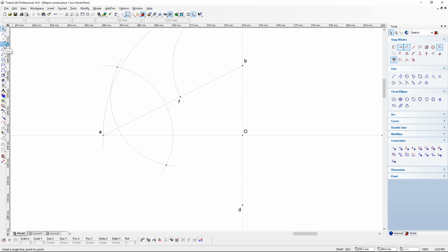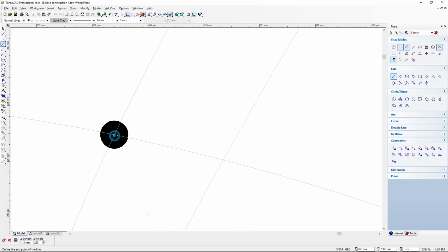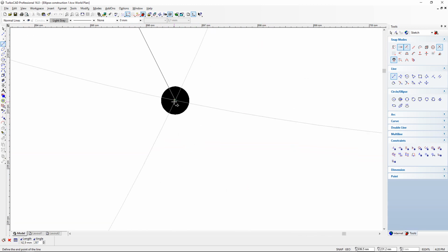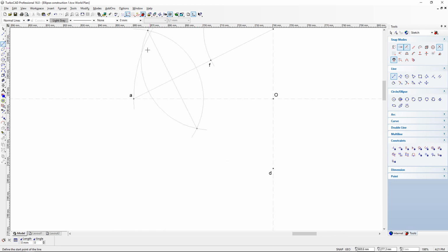to go now to our line option tool, make sure it's on the constructions layer, zoom into the intersection at the top, drag all the way down and snap to the intersection at the bottom. But now the line stops right there, and that's what we don't want. We want to show that it's a construction.